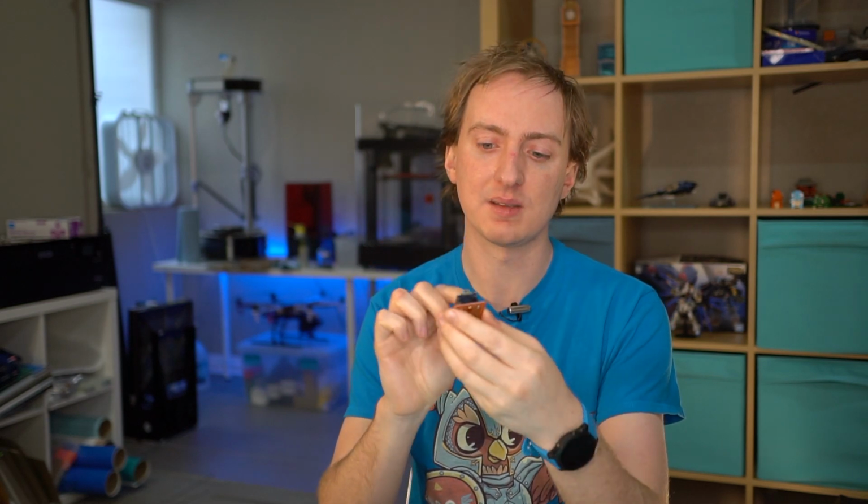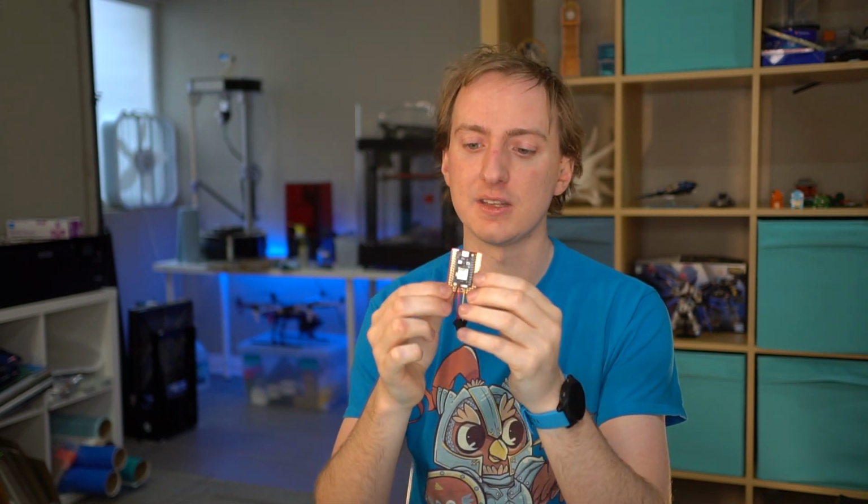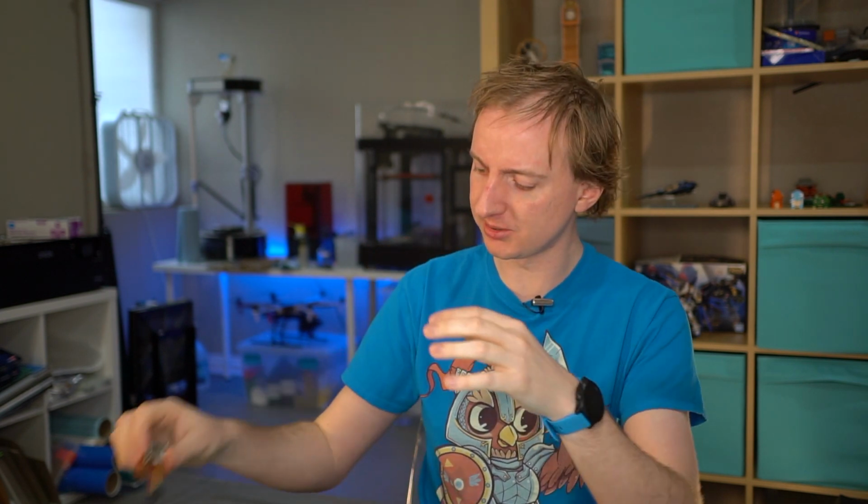And so the core brains of it is this. This is a particle photon. It is a small, I'd say Arduino-ish development board that basically comes with built-in Wi-Fi connectivity. The nice thing about particle boards, they do a Wi-Fi range and a 3G range and LTE range and so on, is they kind of have written a lot of the connectivity stack for you, and they have this nice web-based service where you can push and pull and call APIs natively. So if you're doing a very heavy internet communications-based project, they're a nice leg up to get going, even if they're a bit more expensive.